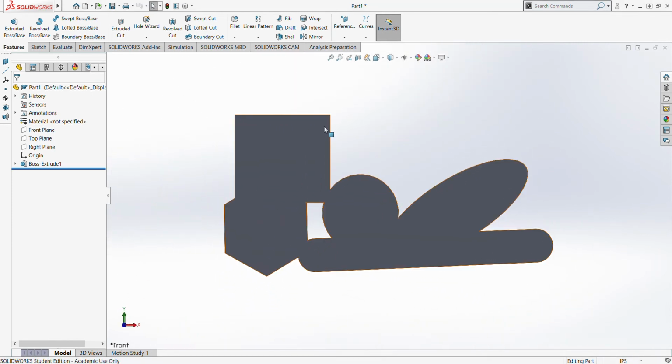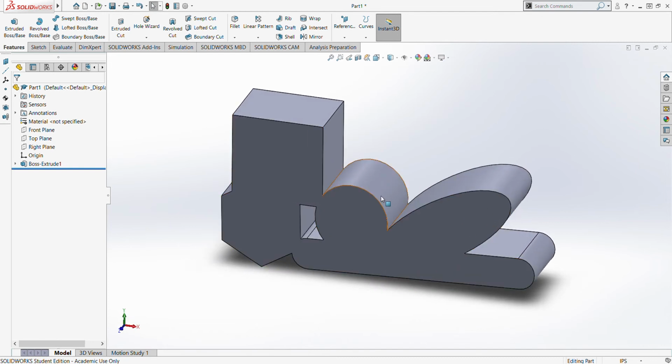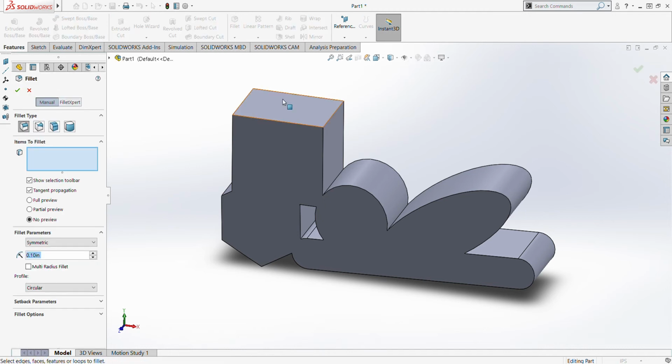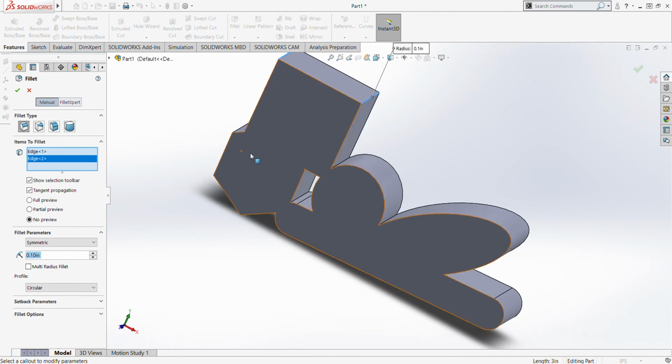So maybe you want to learn how to get rid of some sharp corners. Say these are all pretty round, and you're not happy with this side of the shape. So what you would do is you would use the fillet tool. The fillet tool is right here. You have many different options, but we're not going to do chamfer because we want it to be round. So we're going to do fillet. You go to fillet, and you click on all the edges you want. So say you want this one to be more round. Rotate this. You want these 3 right here to be round.